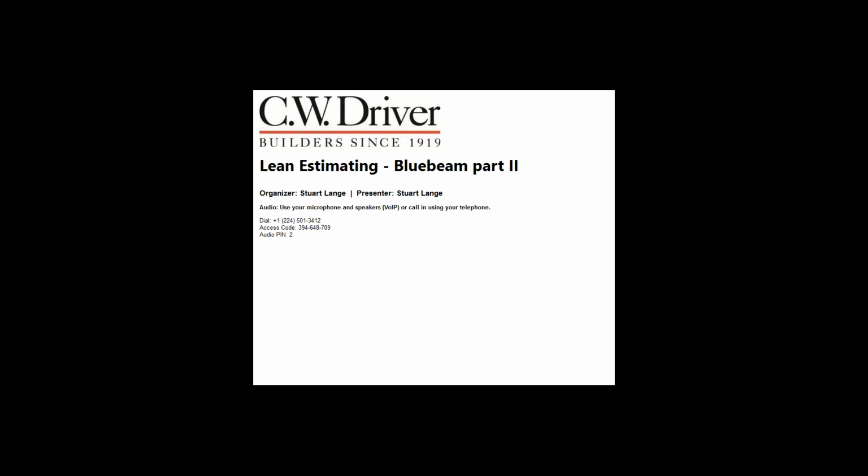That's right. So we start the batch link. So under File, and then Batch, and then Link, and New, and New Batch Link brings you this. So we're going to say Add Open Files, because that's the only one we have open right now. So that's easy, right? Okay. And then if you had multiple files, you could add a folder here, but we're just doing the 1 file. So we could do the architectural, the structural, the MEP, all those at once with the batch link if we wanted to.